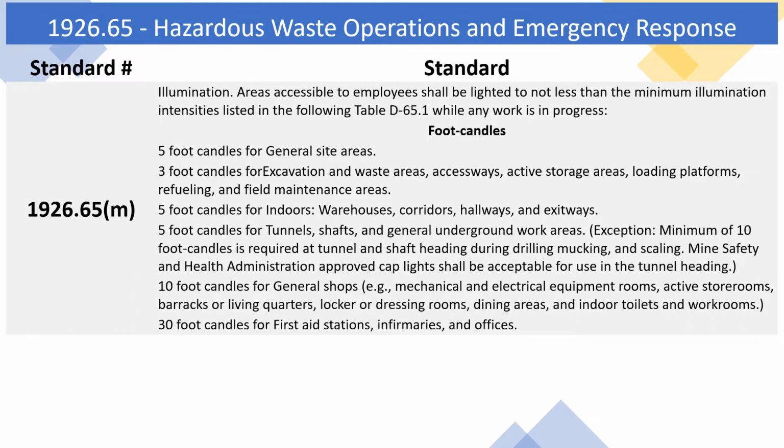1926.65 L.3.2. The emergency response plan shall be a separate section of the Site Safety and Health Plan. 1926.65 L.3.3. The emergency response plan shall be compatible and integrated with the disaster, fire, or emergency response plans of local, state, and federal agencies.